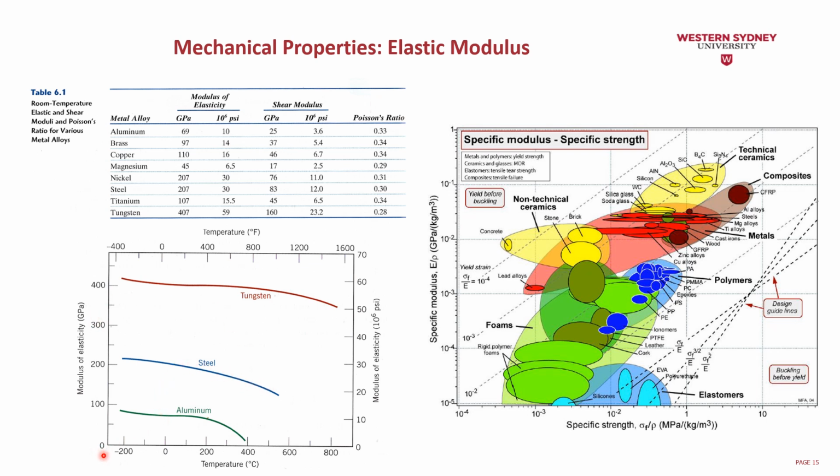You can see here that the modulus of elasticity is higher for the tungsten, up to 420 when the temperature is negative 200 degrees. If I take it to 0, it drops down to 400. If I start to increase the temperature up to 800 degrees, this value drops to 350. That's in gigapascal.